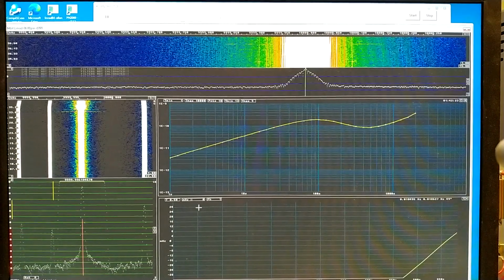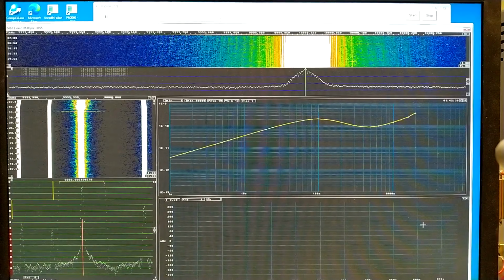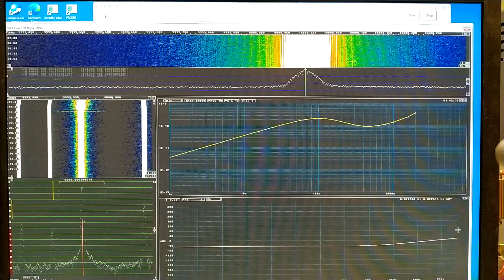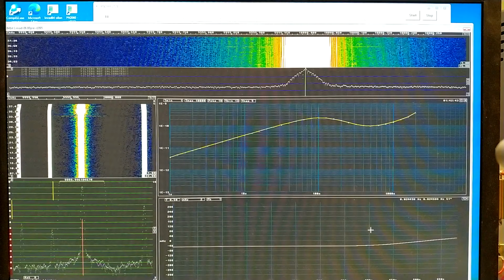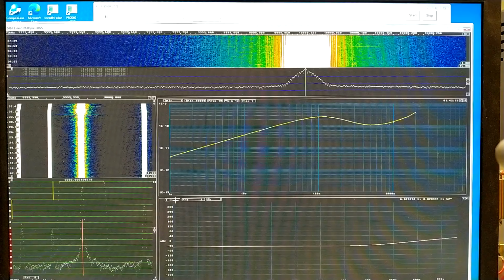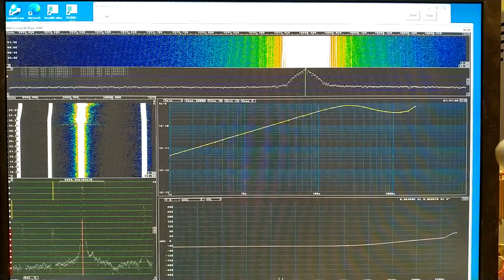I changed the vertical scale by another factor of 10. I make it 2 here. And it seems to be a linear drift now, but strong. I make the horizontal scale slower to see this better. 2 seconds, that's a factor of 10. No, 5 seconds. I can see that the trace flattens out.